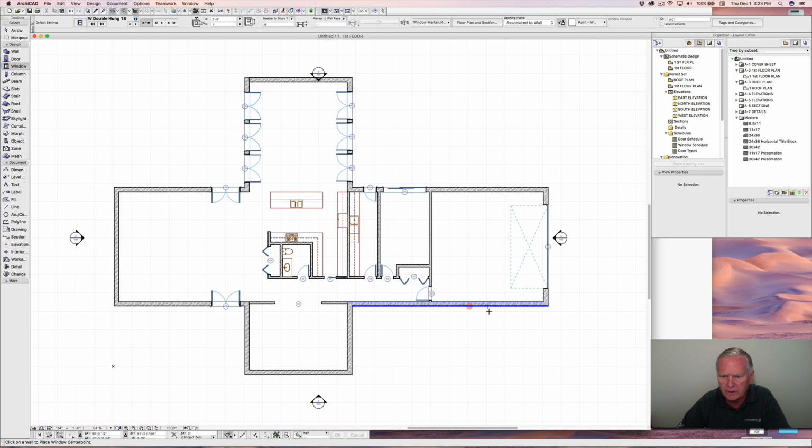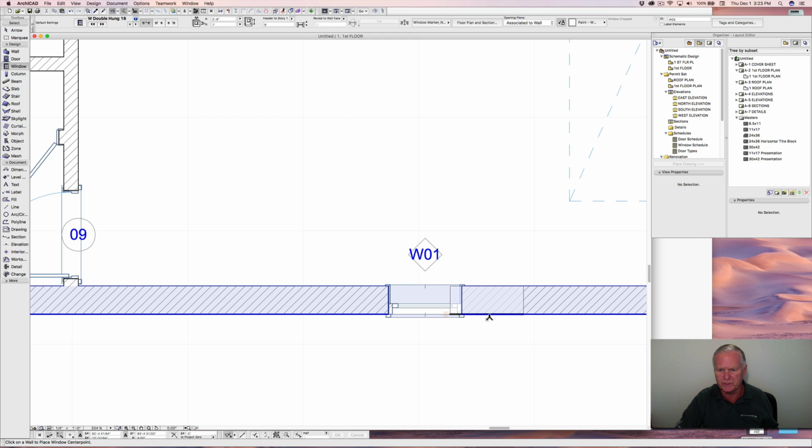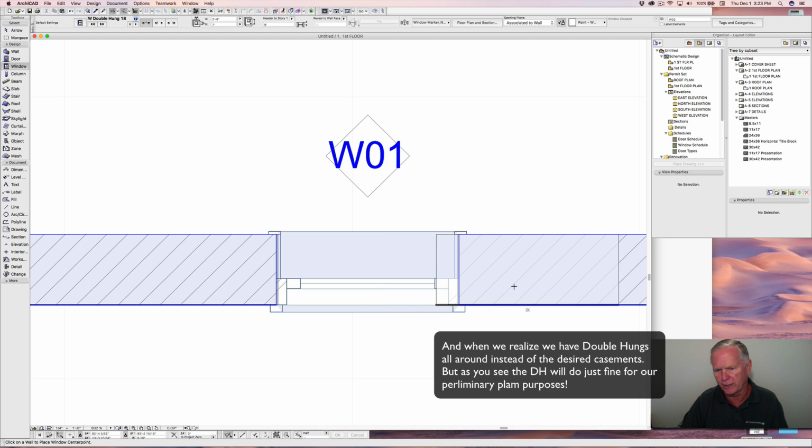I'm going to have 3 of these, and they're going to be separated by 8 inches of masonry. So I'm going to set the first one at center and click on the outside. We'll zoom in on that area a little bit so you can see it. And now I'd like to have 8 inches of masonry in between, and we can decide whether we want that 8 inches to start there, or we get the 8 inches to start on the outside of the brick mold. And even though this isn't technically correct because that brick mold is going to be inset, it will be later when we change this wall into a composite wall. So where you'd see actually the brick and the airspace and the insulated sheathing, 2x6, insulation, gypsum board.